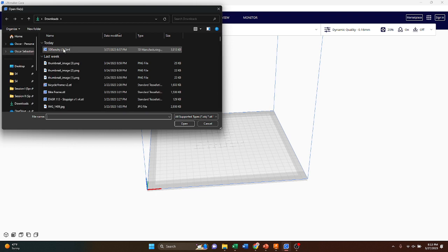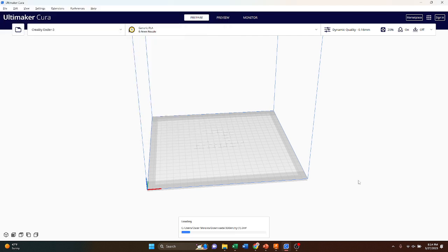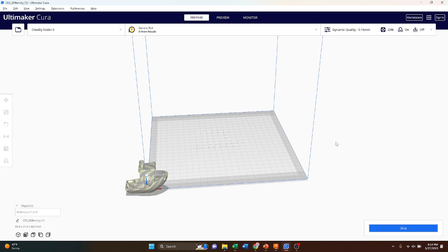For this assignment, we're going to handle the printing of your project, but we still want to show you how to slice parts. So we're going to slice this thing called a Benchy, and this was designed by someone to be a torture test for 3D printers. This part is notoriously very hard to print, and whenever you buy a new printer, it's typically good practice to print this and see where your printer is at. If it does it successfully, that means you have a good one. If it fails, maybe there's a problem with it, or you should have gone out a little more and bought a more expensive one. So this is a universal test to see how your printer works.